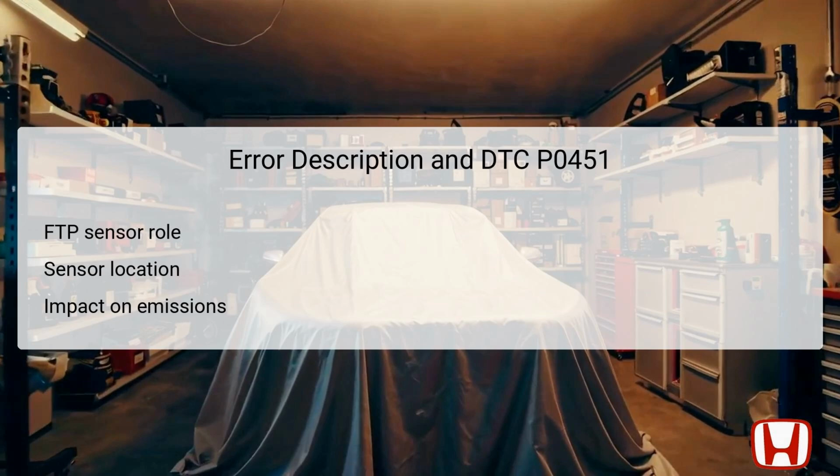The ECM uses this data to ensure optimal performance of the evaporative emissions control system, which helps minimize harmful emissions released into the environment. When the FTP sensor circuit exhibits range or performance issues, it can affect the overall vehicle performance by causing failed emissions tests or triggering warning lights on the dashboard. Therefore, diagnosing DTC P0451 is not only vital for regulatory compliance, but also essential for maintaining engine efficiency and performance.